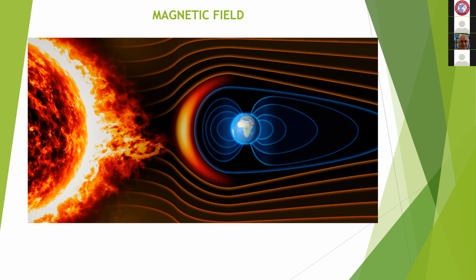And these telluric currents can affect pipelines and railway lines, because pipelines are long, continuous electrical conductors, just like a radio antenna, really. And they pick up these voltages and generate voltages on the pipeline, which make it look as though the pipe is not protected. And it's not true to say that it's a huge corrosion risk. It's more of a measurement risk. But again, when you have the regulator breathing down your neck, the first thing they'll ask you is to prove it.